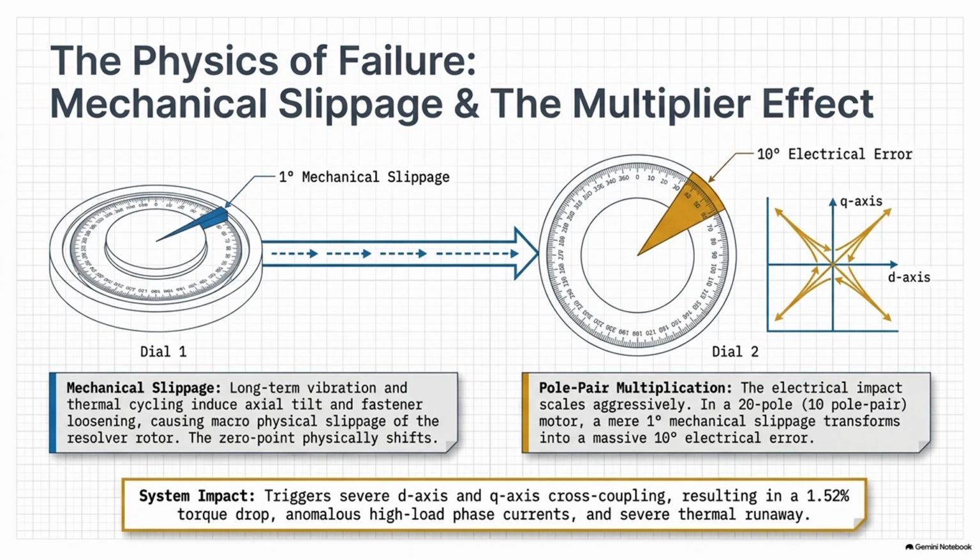But they forget to run the motor commutation calibration sequence on their diagnostic laptop before handing the keys back to the customer. Or, as the source points out, it can even happen at the factory if an automated flashing station accidentally uploads a generic nominal value software package instead of the highly calibrated bespoke software package meant for that specific motor's serial number. So in either scenario, the motor controller is now using old, invalid software offset data to drive subtly different physical hardware.